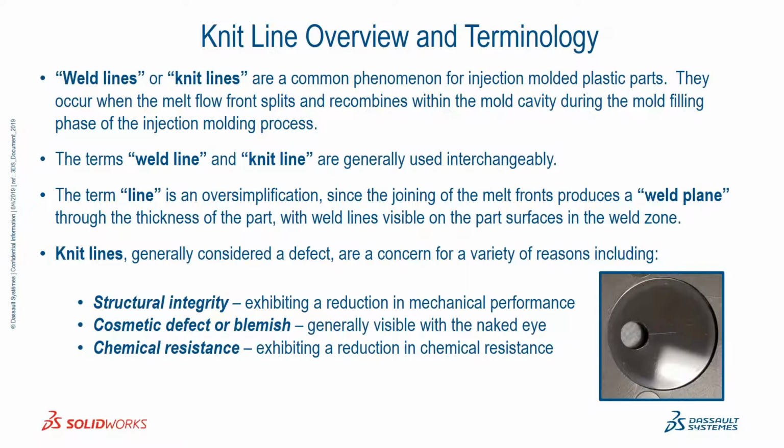which is a very common problem in injection molding. Basically, anytime you have a flow front that splits and recombines during the mold filling process, you end up with this defect, generally called a knit line or a weld line. Personally, I use those words interchangeably.